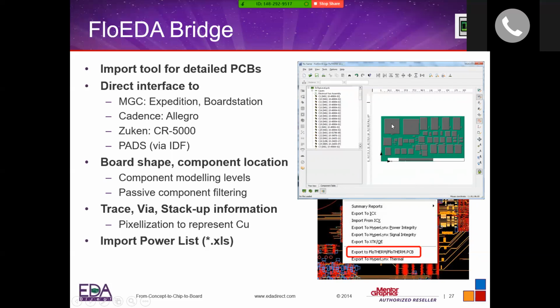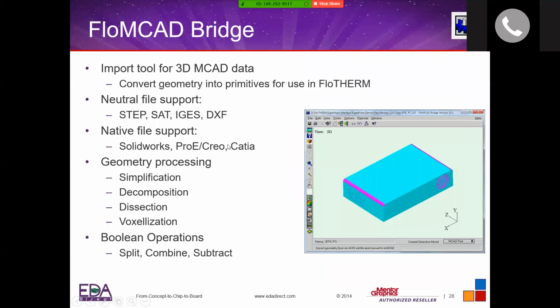And then that's basically it. And here you can also try to add some heat sink. You can also look at the layers routing. Okay, look at the trace effects, trace heating effects in here. Okay, so, and then once you're done with this, and you bring that final model into FloTHERM. So you will do this for the PCB side.